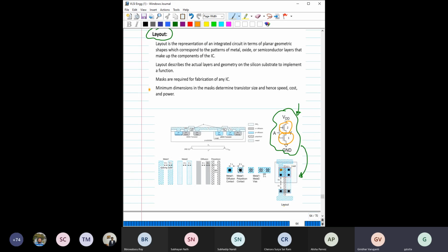So this is actually the tap part, for the contact. This is the polysilicon part, right? This is the polysilicon gate. And these are the terminals, the drain terminal and the source. So this is the drain terminal for this PMOS, and this is the drain terminal for NMOS.